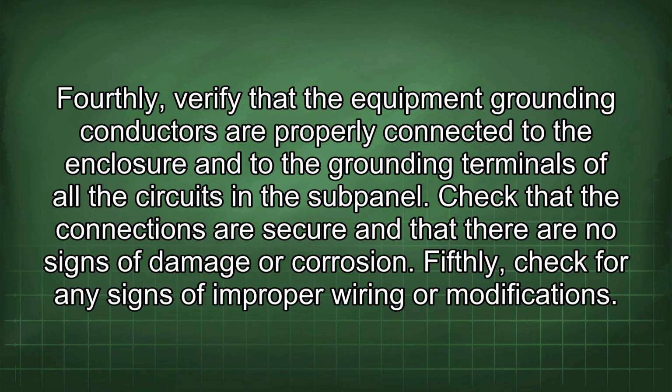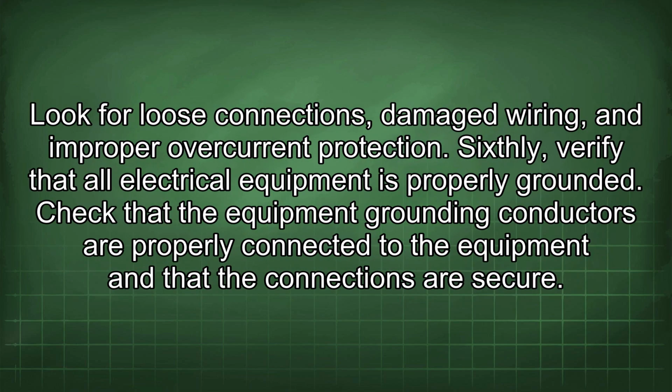Fifthly, check for any signs of improper wiring or modifications. Look for loose connections, damaged wiring, and improper overcurrent protection. Sixthly, verify that all electrical equipment is properly grounded. Check that the equipment grounding conductors are properly connected to the equipment and that the connections are secure.